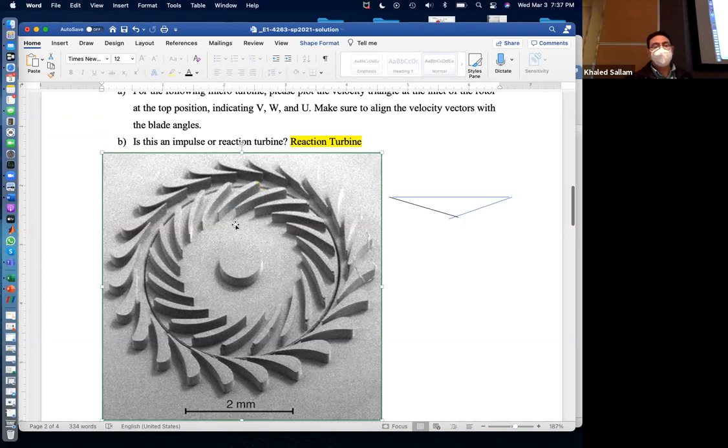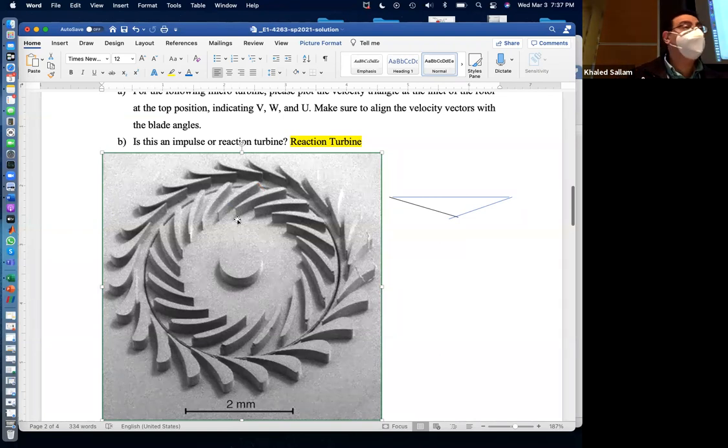Imagine a compressor, and this rotor will be connected to a pipe, a duct, and the air will be rushing into that rotor. It will come all radial because there is no reason for the flow to come with a twist. We are sucking it in, and it will just come, surrendering itself to us. It comes from the atmosphere behind, rushing toward the vacuum that you created here. And why is the vacuum created here? Because as this spins and kicks those particles out by centrifugal force, they create a vacuum behind them.